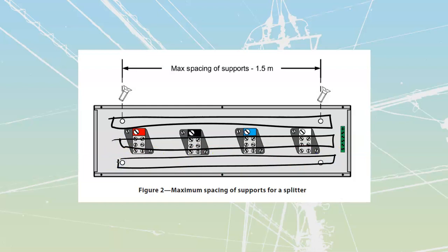These long bus bar type of splitters are particularly susceptible to fault currents, where if I were to have a massive short across, for whatever reason, either inside of the splitter or across cables that are attached on the outside of the splitter, if they would get shorted together, we would deliver a large amount of fault current through them. Splitters are generally used where we've got our larger components inside of the service. As soon as we deliver that fault current through there, a large amount of current is always going to result in a large amount of magnetic flux that we're going to have.